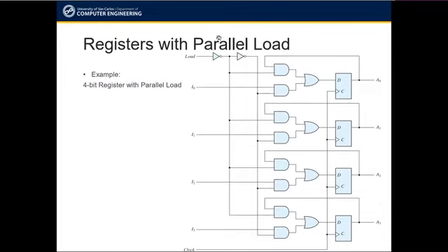What parallel load does is introduce a set of inputs to the circuit simultaneously, just like what I0 to I3 does here, and in most cases it is done to specify a set of values on several flip-flops, just like in this circuit. Please take note of the term parallel load, for it will be often used in the succeeding discussions and lectures.